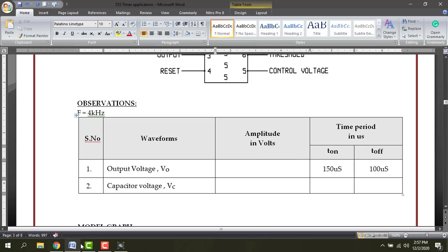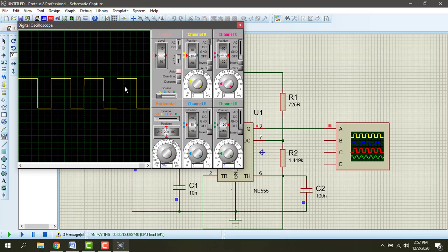And the amplitude, that is voltage. Voltage is the vertical height. The total vertical boxes 1, 2, 3, 4. I'm going to change the voltage scale into 1, exactly.